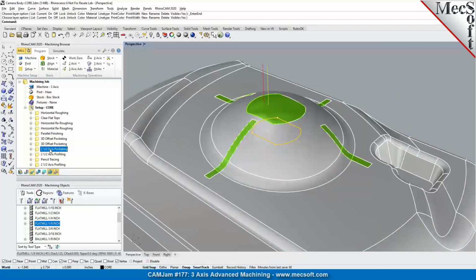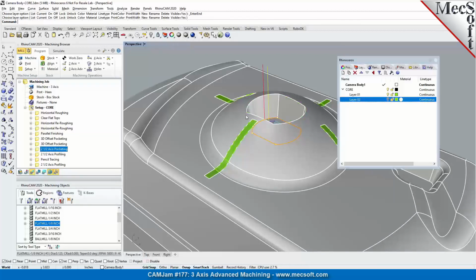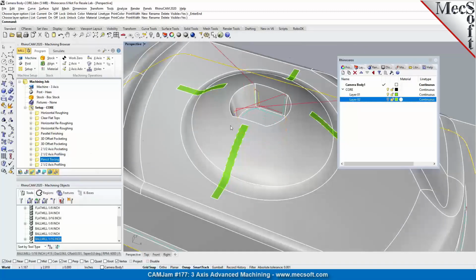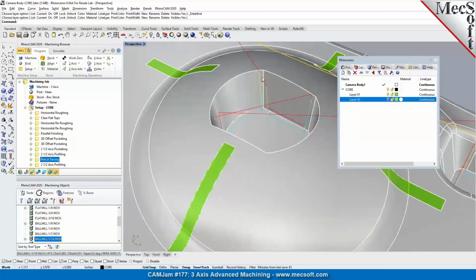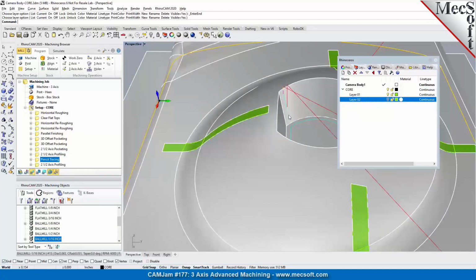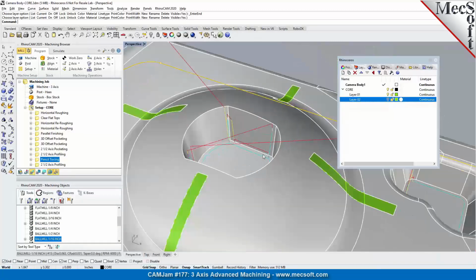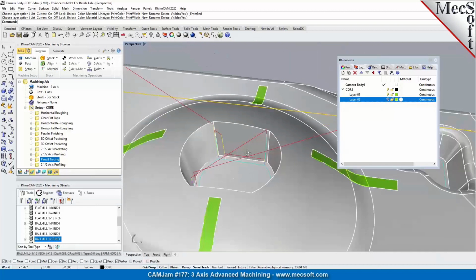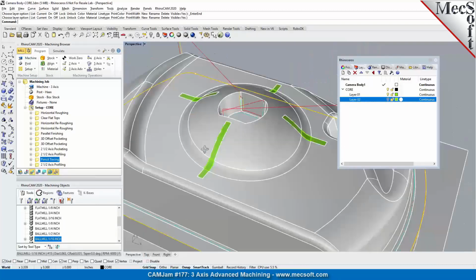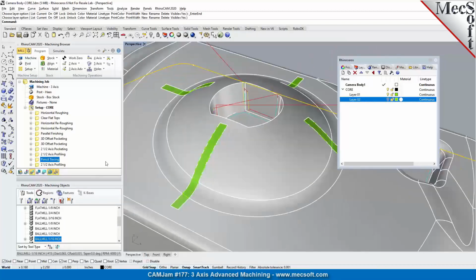And finally, you can go ahead and expose those areas by hiding those surfaces to generate your finishing toolpaths, or you can even do a combination of both 2 and 3 axis toolpaths to finish off those pockets. Or if you'd like to do a pencil tracing operation to go back and clean up, you can see this pocket has a draft on it, so the pencil tracing will be able to identify those bitangencies to clean up and result in a nice finish. Again, in this particular case, we are using a radius cutter, like a 16th inch ball mill cutter, to clean it up.